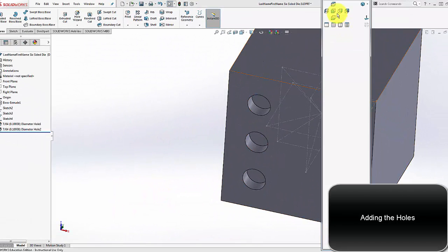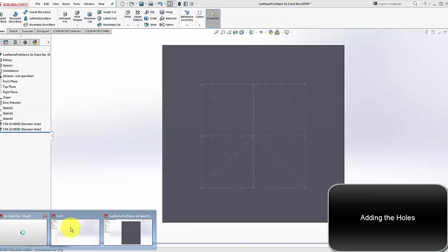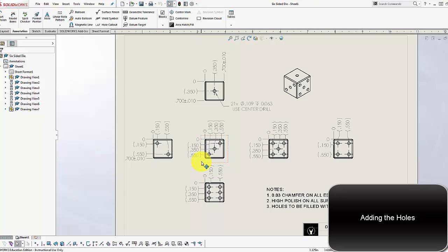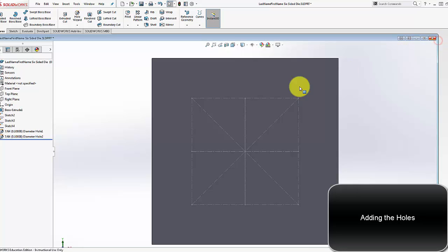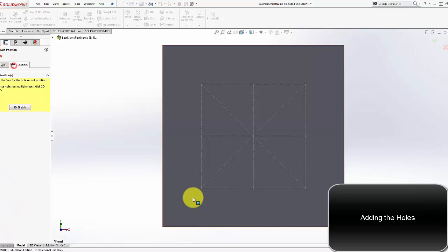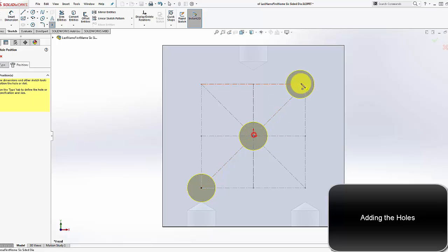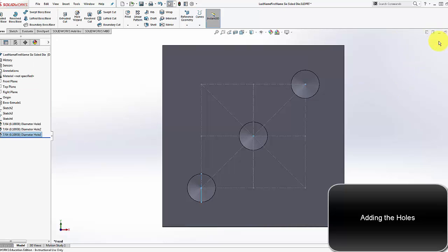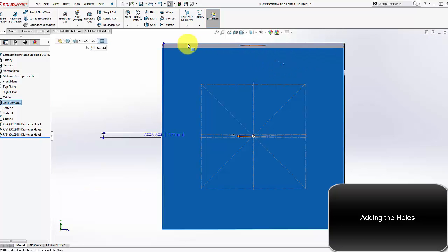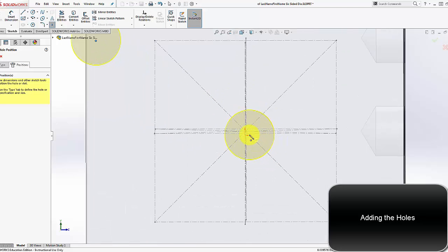So next up, I'm going to do the front face. The front face is the 3, and there's something slightly tricky about the 3 and the 4. You want to make sure you get the correct orientation. So if we look at our example, the 3 should be going up and to the right, whereas the 2 goes down. So we'll come back here, go ahead and make another Hole Wizard, and then make our 3: 1, 2, 3, and then we can come over to this face and make our 3, oh, accidentally added that one.